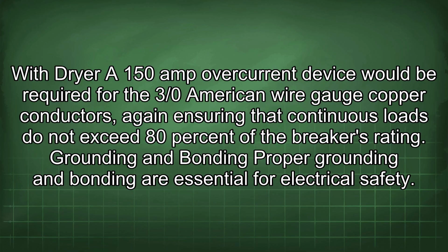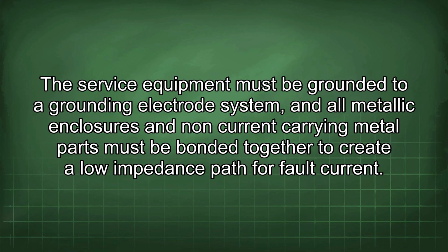Grounding and bonding: proper grounding and bonding are essential for electrical safety. The service equipment must be grounded to a grounding electrode system, and all metallic enclosures and non-current carrying metal parts must be bonded together to create a low impedance path for fault current.